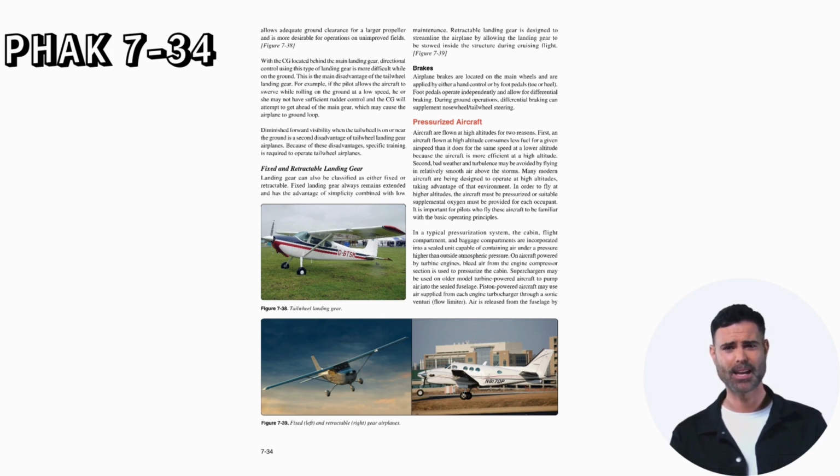In order to fly at higher altitudes, the aircraft must be pressurized or suitable supplemental oxygen must be provided for each occupant. It is important for pilots who fly these aircraft to be familiar with the basic operating principles. In a typical pressurization system, the cabin, flight compartment, and baggage compartments are incorporated into a sealed unit capable of containing air under a pressure higher than outside atmospheric pressure.